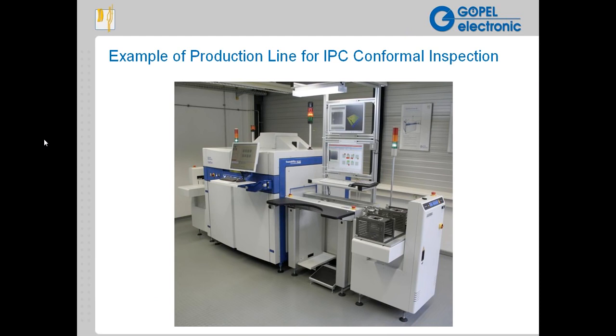Looking at a few requirements that AXI really addresses, one of the requirements that is a challenge these days is inspection of hidden components. As you can see from this AOI image, we have a device underneath the metal shroud in the center right. That shroud is not a heat sink. It's, I believe, just a radiation shroud. So while it has significant density, the density is such that we can penetrate it with X-rays.